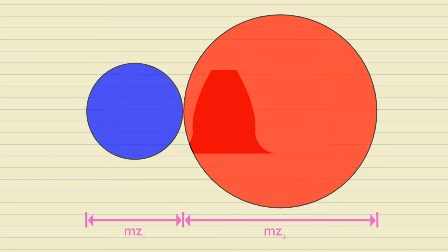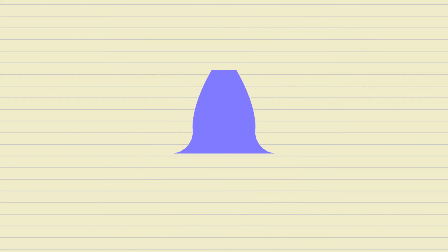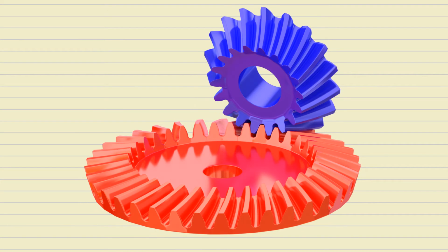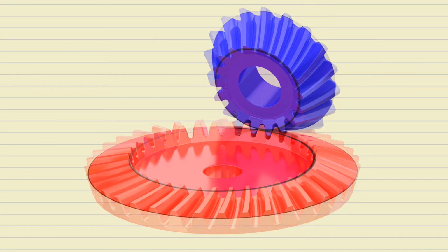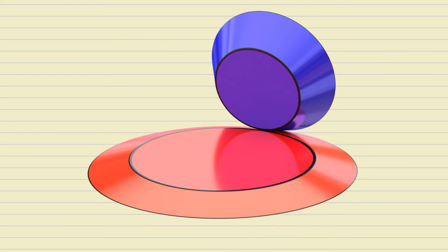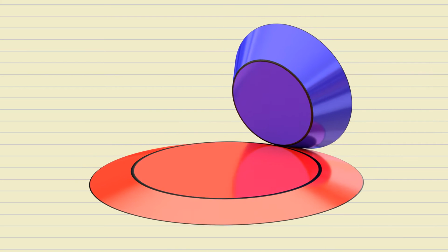The sides of the gear teeth are usually curved, and the curve, called the involute, can be described with a pair of simple parametric equations. Let's go back to bevel gears. Conceptually, a pair of mating bevel gears can be represented by two touching cones, called reference cones.